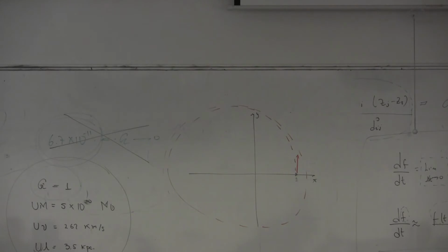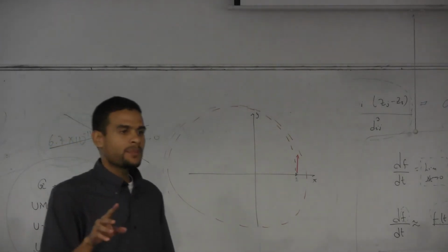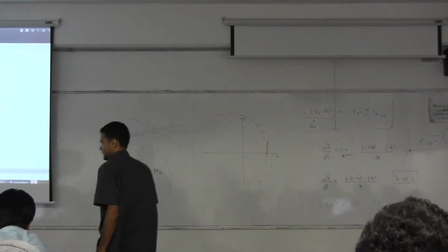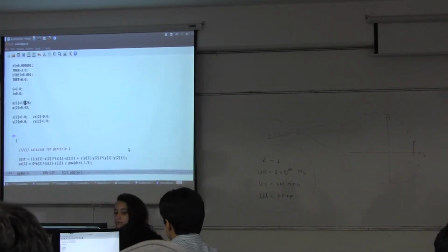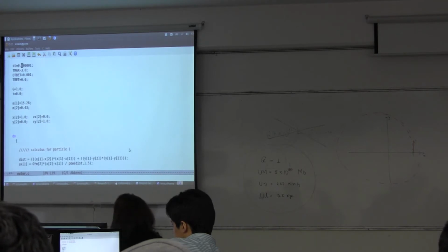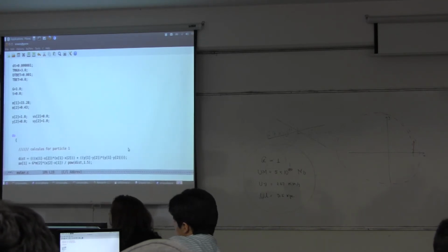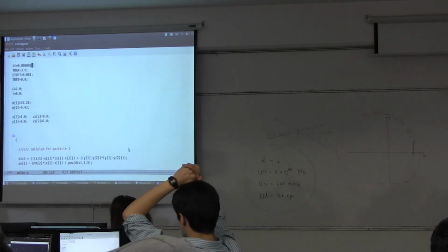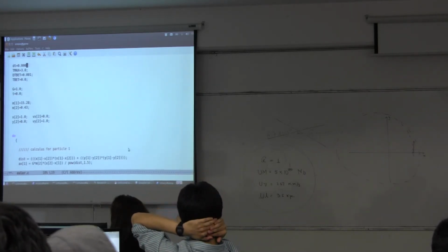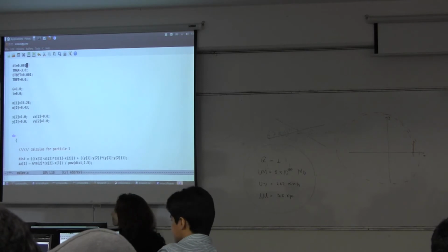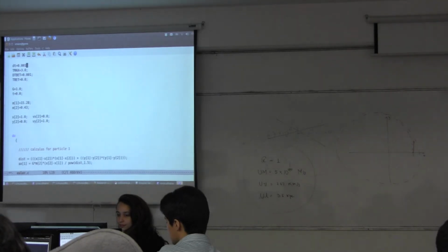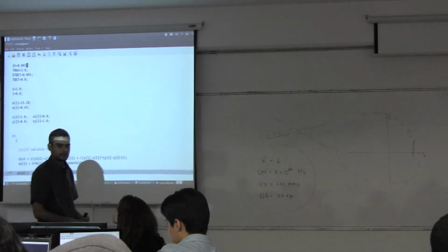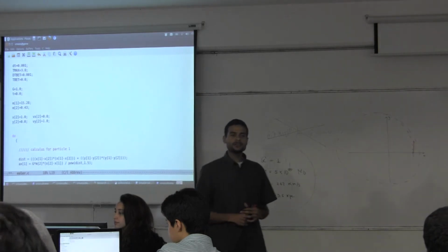Now, I was telling you that there is a very important parameter for this kind of problems, or for this kind of simulations. That parameter is the integration time step. Let's change the integration time step. As you can see, for me, the integration time step is this one, and I chose a very small one. Let's give some very crazy number. 0.001. Please change that number.